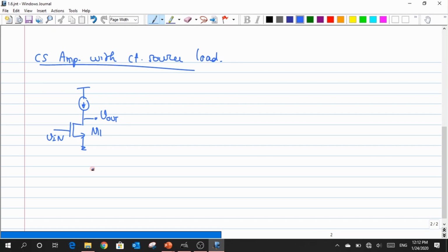Right? So now how would I realize this current source? So how do I physically realize this kind of current source? So what am I supposed to do? Yeah, so I have to bring one of the MOSFETs into the saturation regime, because in the saturation regime the current is almost constant. Okay, so what type of MOSFET do I have to choose? Can I use an NMOS transistor, or do I need to go for a PMOS transistor?